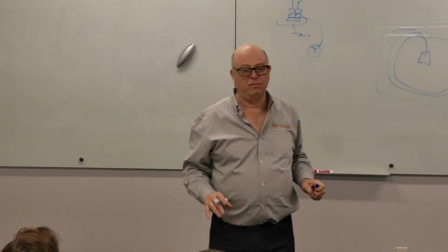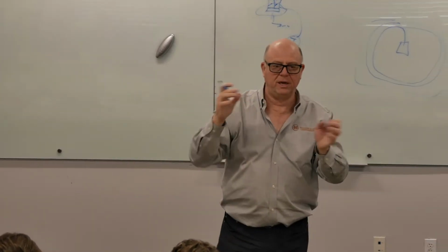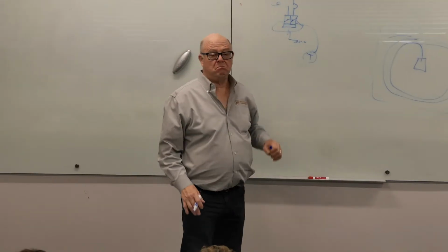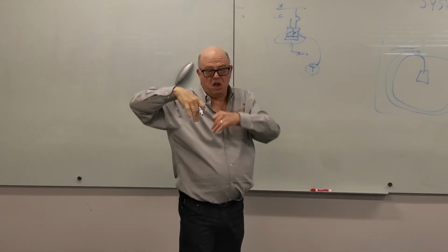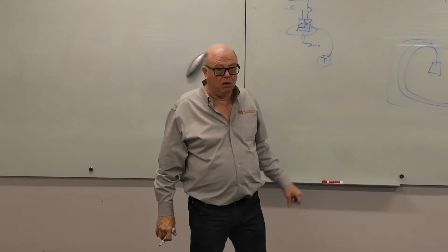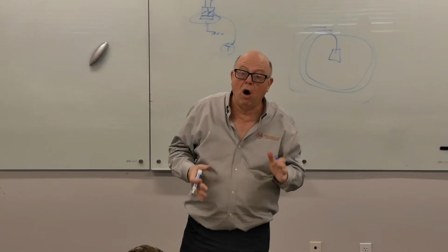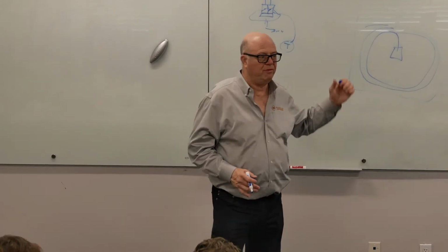Title 24 from way back didn't want you mixing mechanically cooled and mechanically heated air. But you could work with the cooling air, take it down to a minimum. You could work with the heating air, take it down to a minimum. You could shut either one off. There was generally a ventilation air code requirement, so you'd have to have some air going in.